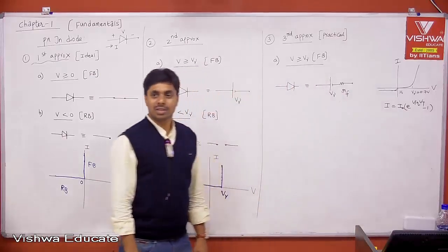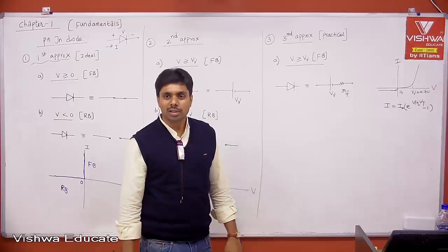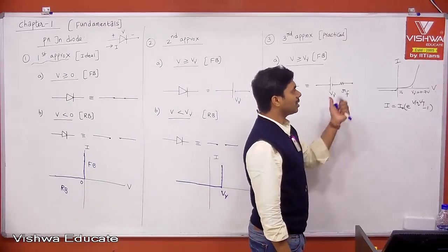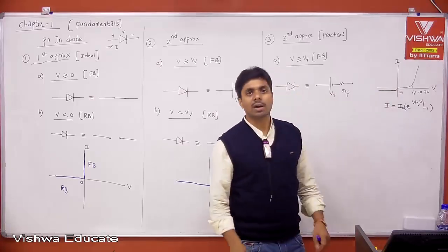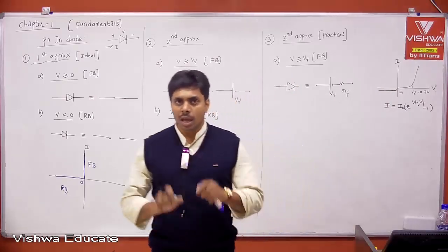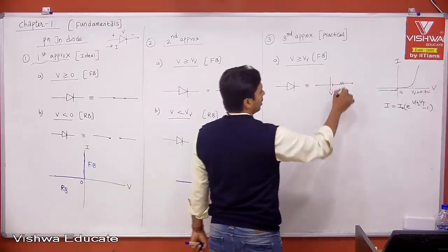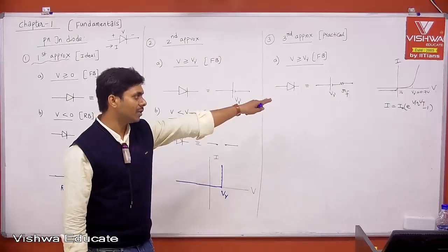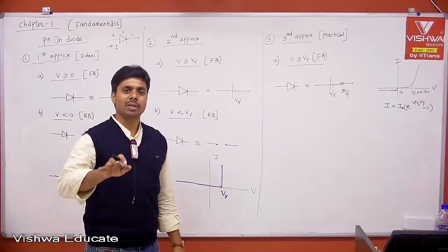When I speak about resistance, we know that it is non-linear. If it is non-linear, then at what voltage? That depends on the voltage. Therefore, this is what people define as the forward resistance or the forward dynamic resistance. I'll explain what that forward dynamic resistance is. But that is what is represented with the resistor, because it will have some drop. The voltage drop is not always V gamma, not 0.7. It will increase like 0.7, 0.71, 0.72, 0.73.